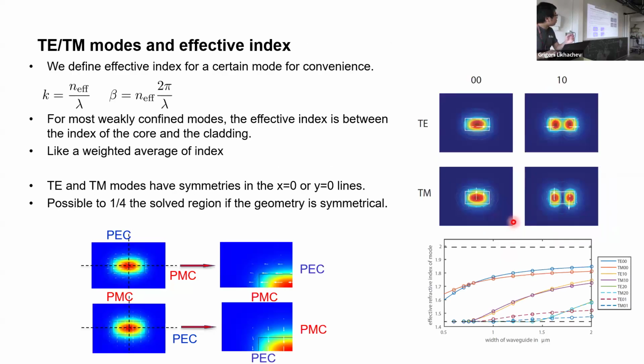Here, just to show how we usually name our modes. This thing we call the TE00 mode. Basically, you have only a single bump of electric field that is concentrated along the geometric center of your high index waveguide core.